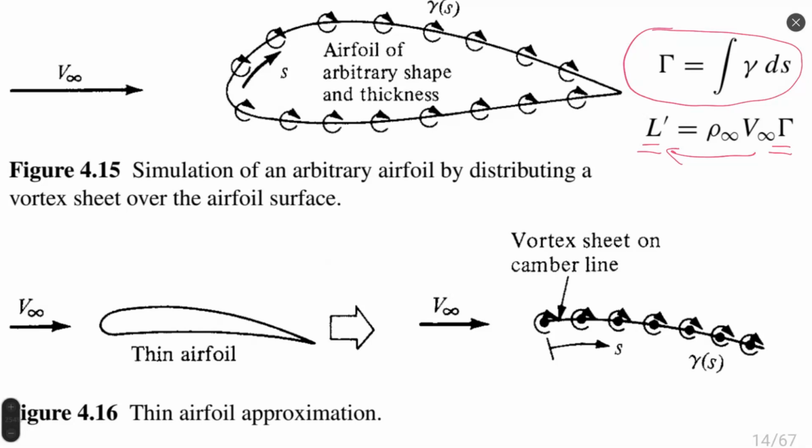It means when we know the circulation, when we analyze the velocity field around the airfoil, when we know density and velocity at infinite distance, not on the airfoil, we can calculate which lift is created by this body. So analyzing the flow around, we calculate the force on this body. Very nice, all right? This is in general. But what is the problem for this model, this two-equation model?